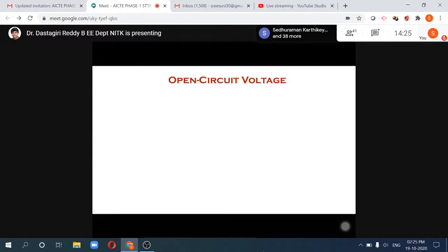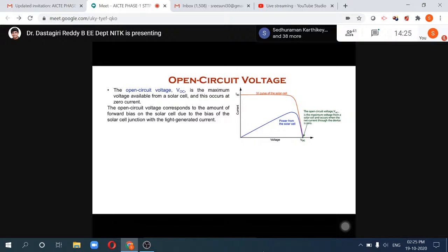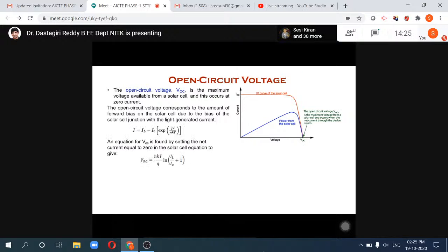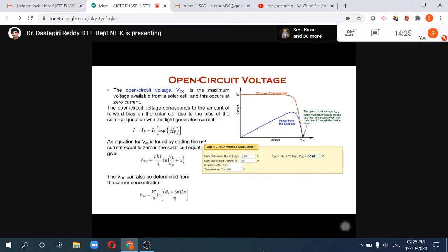Now, when it comes to open circuit voltage, there are some factors affecting that. That is quite straightforward: what is the junction you selected? We already discussed the trade-off when you define the junction voltage of a diode, in the selection of the semiconductor itself. We compromised on the voltage. If it is a bigger voltage, then there will be less current.